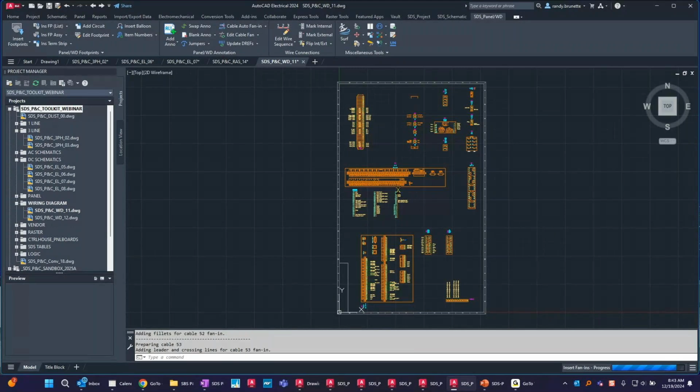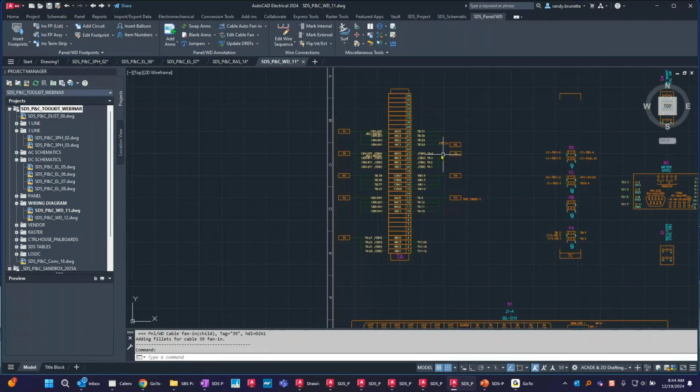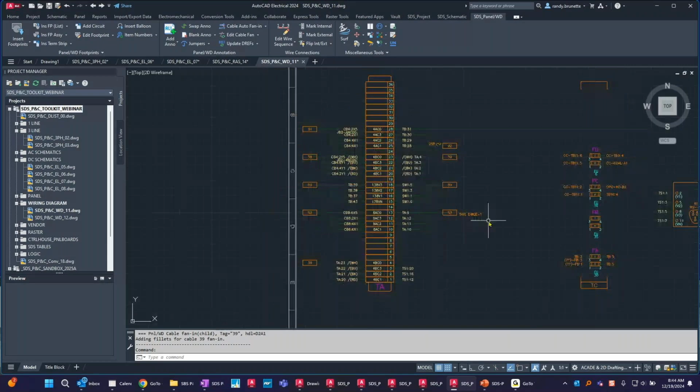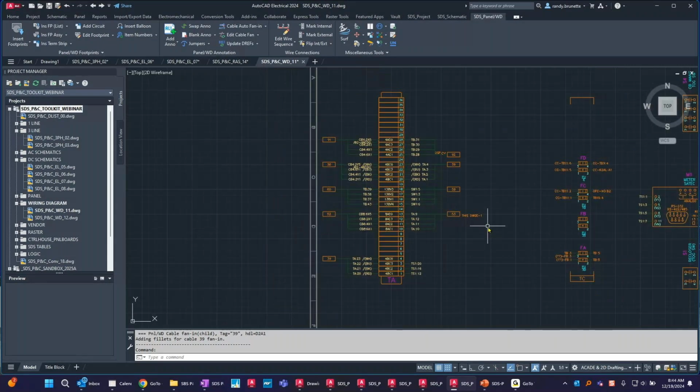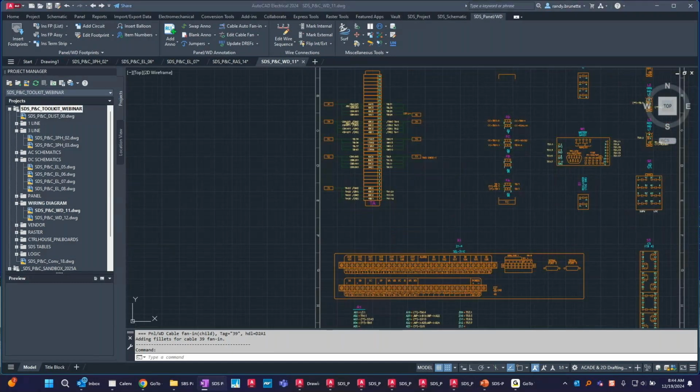So it's reading all of those places. It's trying to avoid any crossing lines that might take place. And there we go. We have all of our cables automatically entered. Notice this one's even telling you on this particular cable, we have 2 spare wires that we could do. This one is telling us that 53 is continued on this drawing under E1, which is right over in here where the other cable is ending up and so on. Right? Pretty cool stuff that's going on with that.